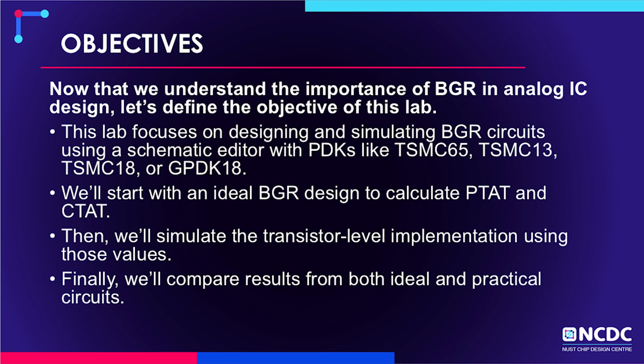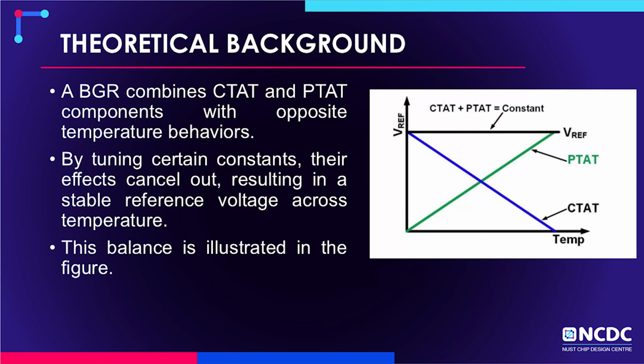This lab focuses on designing and simulating BGR circuits using a schematic editor with PDKs like TSMC65, TSMC13, TSMC18, or GPDK18. We'll start with an ideal BGR design to calculate PTAT and CTAT. Then, we'll simulate the transistor level implementation using those values. Finally, we'll compare results from both ideal and practical circuits. Let's start by understanding the theory behind the BGR circuit before moving on to the actual design.